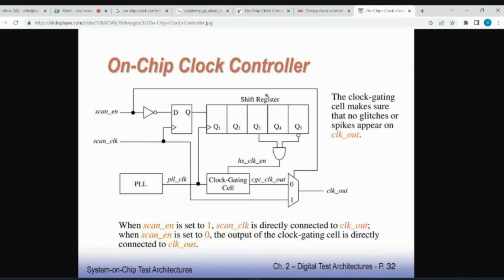So this particular activation of OCC, we will program it in our pattern generation environment in such a way that one or two or whatever number of pulses you want at speed clock, that particular high frequency clock that you need, those clock pulses you will generate only when required, and only in that capture stage. So you will program it accordingly. We will learn that programming of the OCC during the ATPG stage, not now.